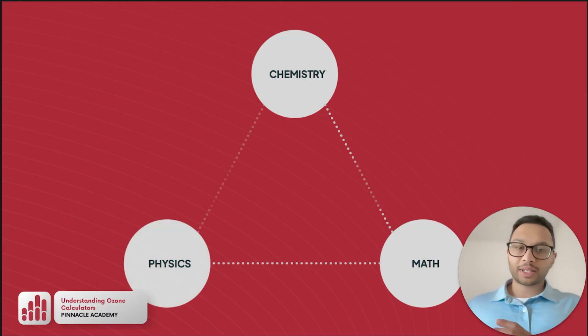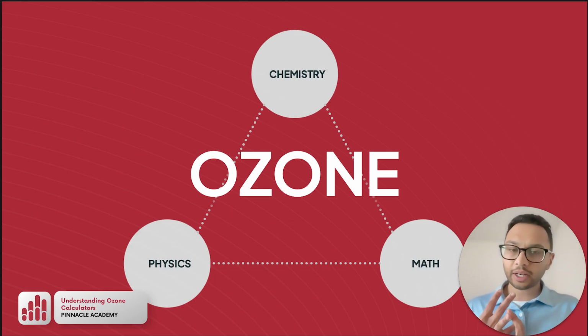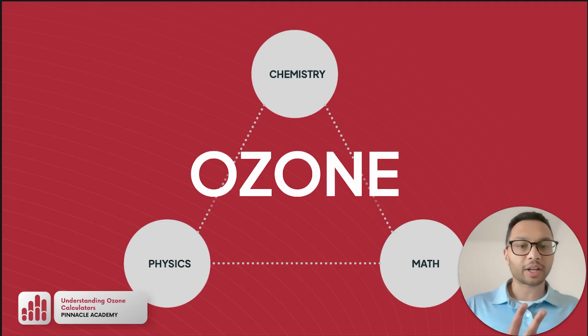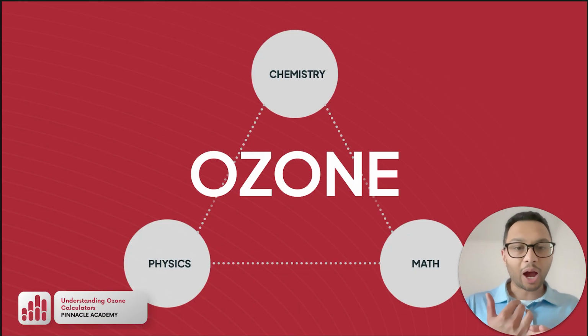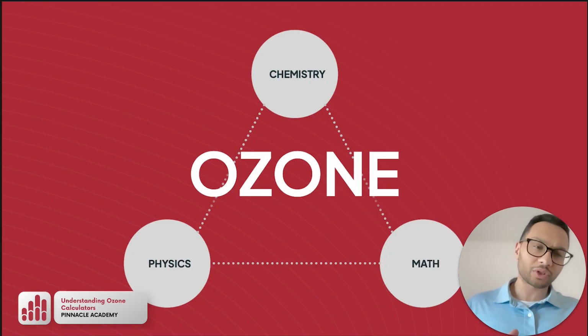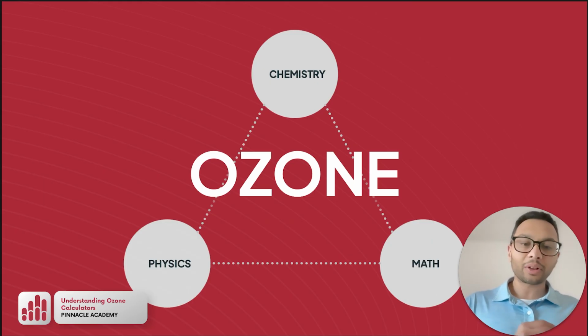So ozone systems sit at an intersection point between three core principles. You have physics, chemistry, and math. Let's look at it from the chemistry standpoint. Ozone is a strong oxidant. It's what drives the disinfection and breaking down of contaminants. You have the physics standpoint, which is all about the gas to liquid transfer. How efficiently are we getting the gas into the water? And then from the math standpoint, we qualify everything based on dose, mass, flow, and efficiency. If you don't understand all three, you cannot properly design and optimize an ozone system.